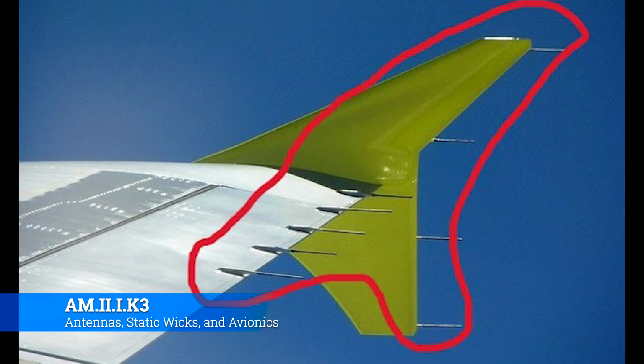But the more radio traffic there is on any aircraft, the more likelihood that you're going to end up having a static discharge happen. This becomes very, very important for your safety, but it also becomes very important when we're handling any sort of electronics. Because remember, our ESD practices are there to help curtail some of this accidental static damage that could happen whenever you're pulling boxes out of an airplane.